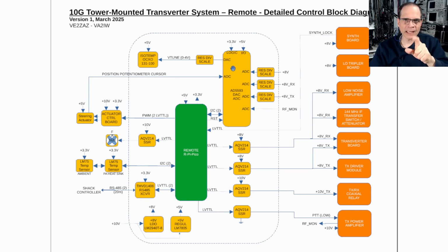What is it going to send? As far as analog voltage, I'm going to be able to tune the ovenized oscillator that's on the same board. And this is the 10 megahertz reference that will sync my whole RF chain. So it's a small can, but it's an ovenized oscillator. And I will be able to tune the 10 megahertz frequency exactly to the right frequency so that I put out 10.368 exactly using the DAC output of that chip.